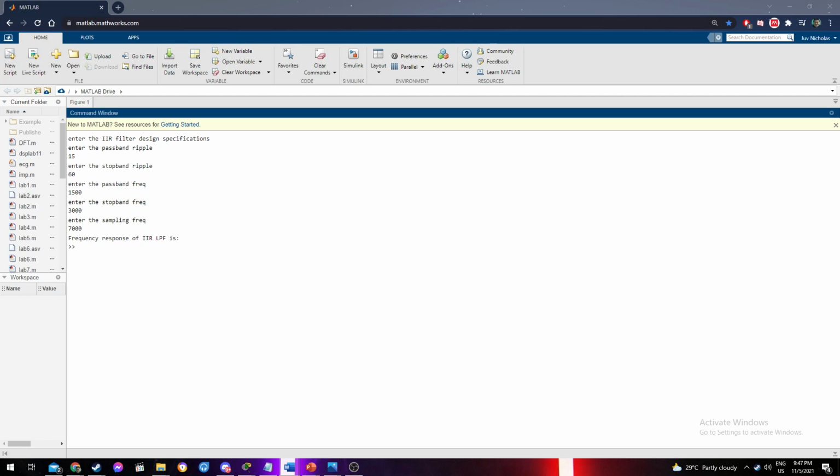Unlike FIR filters, their phase characteristics are not linear, which can cause a problem to systems which need phase linearity. For this reason, it is not preferable to use IIR filters in digital signal processing when the phase is of the essence. Otherwise, when the linear phase characteristics are not important, the use of IIR filters is an excellent